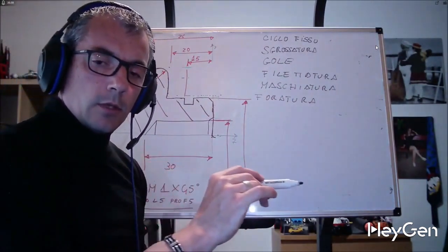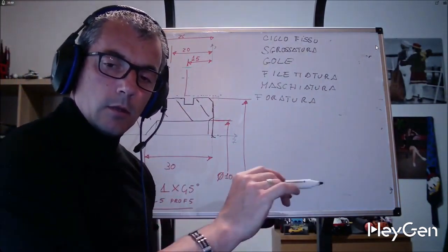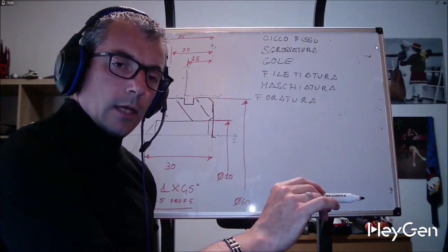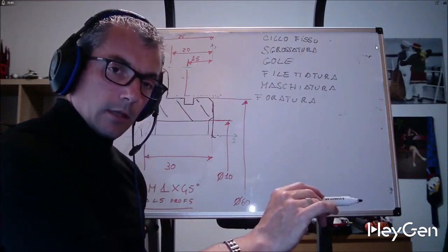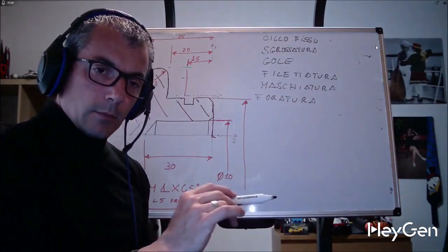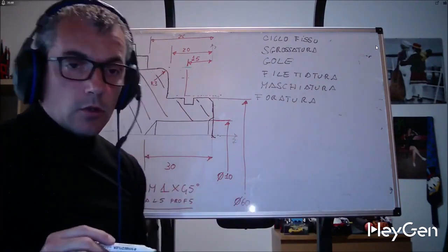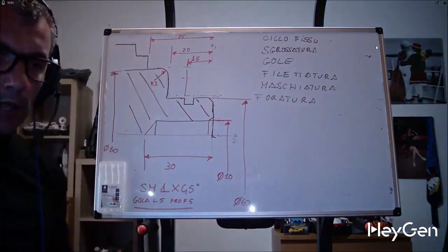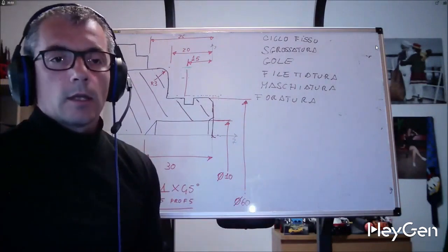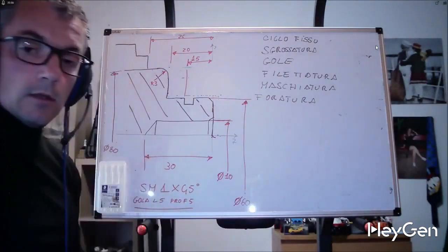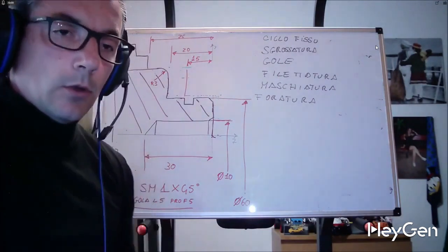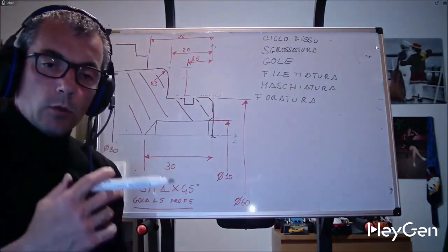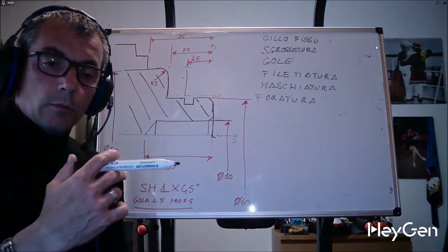It can only be done with a fixed cycle because you need to enter at a certain feed rate, gradually slow down the spindle speed until it completely stops, reverse the direction of rotation gently, and exit. Therefore, tapping is not programmable in standard ISO, but requires a fixed cycle.